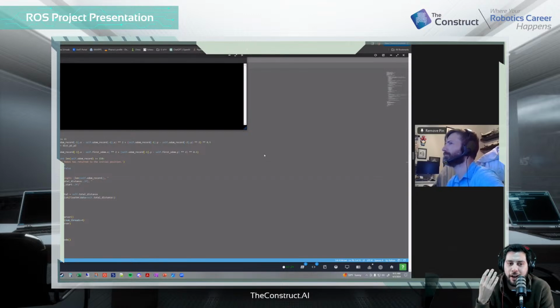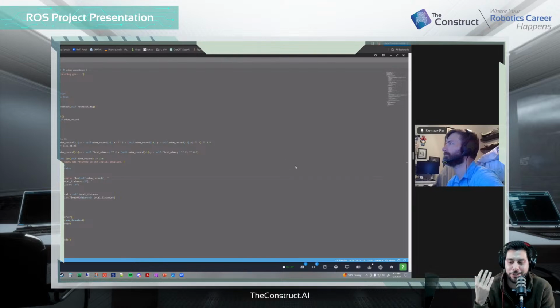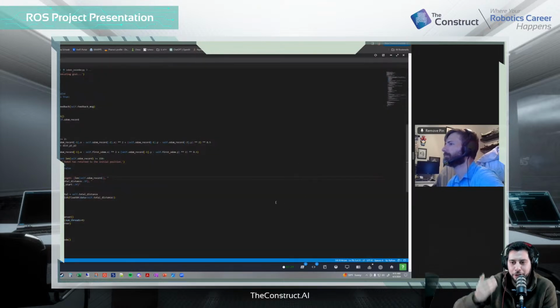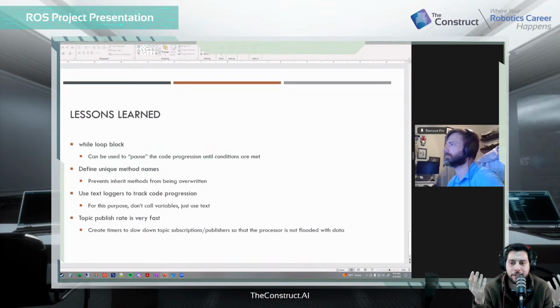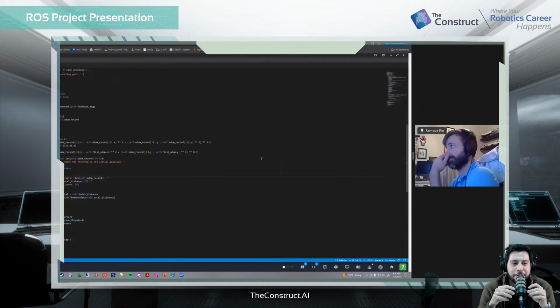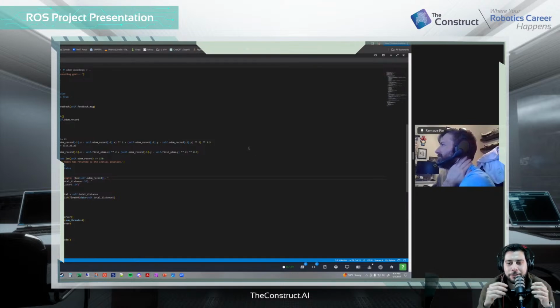So basically, the wall finder is better implemented, in my opinion, in an action server. But we have to show all three things you can do with ROS 2. In that case, you can add those states as feedback. When you run it, you don't block everything, so you're not just waiting for the response. You can do other things and take action if the feedback goes incorrectly or something happens. I thought it was really interesting that you were inadvertently changing that service server into what an action server would do for you. So now you know for next time. Yeah, I didn't think about that.